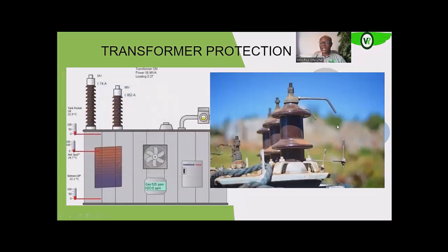You see that the upper part of this arcing horn is connected to the live part of the transformer. Remember, this is a bushing. This bushing insulates the live part from the body of the transformer, or the non-active part of the transformer. The other part of the arcing horn is connected to the frame, or to ground, of the transformer. Between here and here, there is insulation caused by the air in that gap.